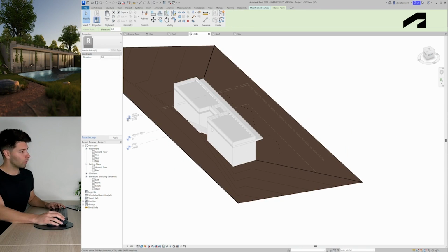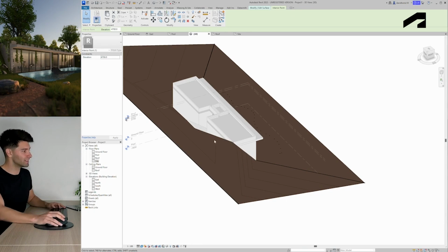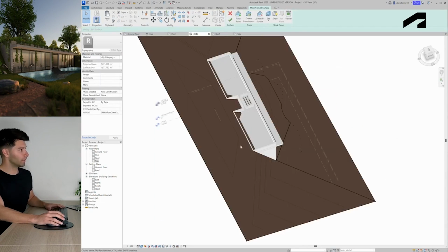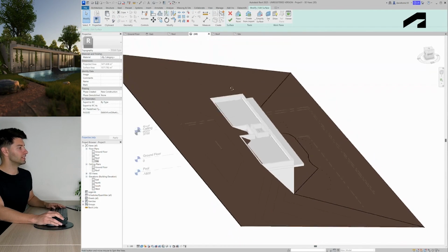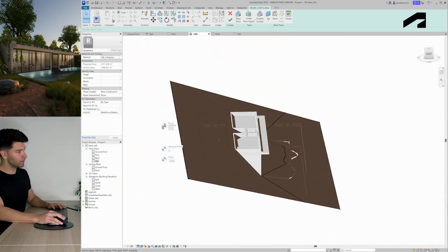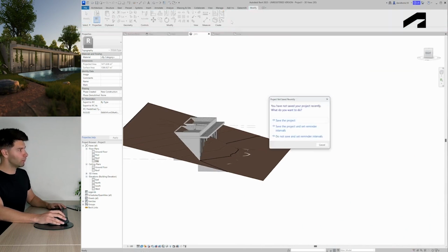The hotspots in the corners where our ground is actually going to connect to our roof, I do genuinely want that to go to the full 4.7 meters. So that ground interacts and naturally slopes all the way past our actual roof garden. Which, if I go back to the site floor plan now, also means these 3 hotspots need to be at 4.7. Coming back into 3D, once again, we can see that 4.7 has been created. Now that we've gone ahead and adjusted all of these nodes to suit the levels regarding our actual building, we can go ahead and press OK.